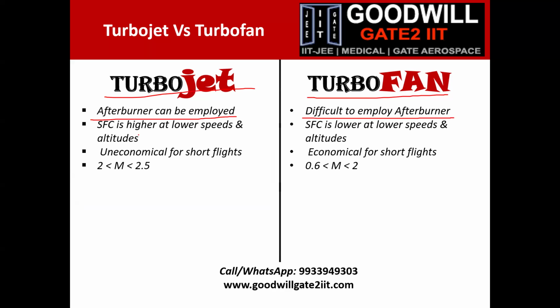All right. For turbojet engines, fuel consumption is higher at lower speeds because it is designed to travel at high speeds and at high altitude. So if you travel at low speeds, it doesn't mean you cannot travel. You can, but your fuel consumption will be very high. You should move to high altitudes as early as possible.